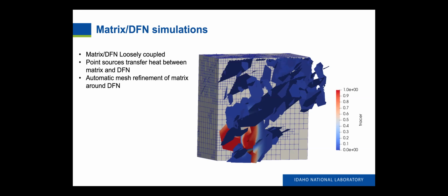I think the most promising way, and we're just finishing up the work right now, is the IPG. We're doing a mix between continuous and discontinuous Galerkin with the penalty method, or the interior penalty. That seems to be a really promising way to actually have those things open up. Right now with the flow, once we move away from having a 2D plane that's contiguously meshed, then we have to sort out solving that fluid flow in that crack as it opens. That's a little bit more of a challenge to solve inside the crack if it's actually moving explicitly. So we're looking at things like maybe a lubrication type equation to solve in there to be a little less cumbersome. But that's still a little bit in the works for right now.